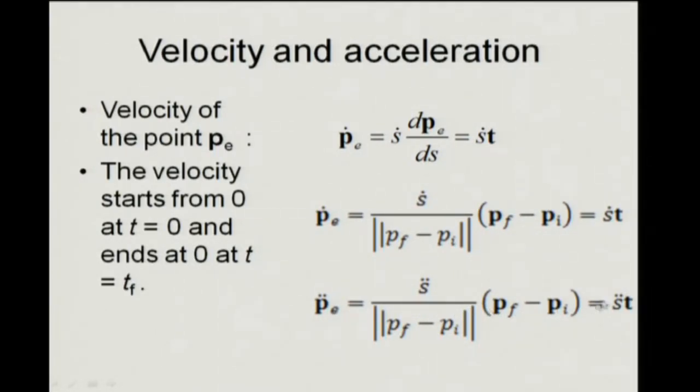Now why do I need this? Because I can then very quickly write down at the joint level what is the local velocity, the joint velocity and the joint acceleration, by doing a Jacobian control or something similar to that. And I can use all these inputs. When I did the linear interpolation or interpolation on joint axis, I said there could be so many specifications.